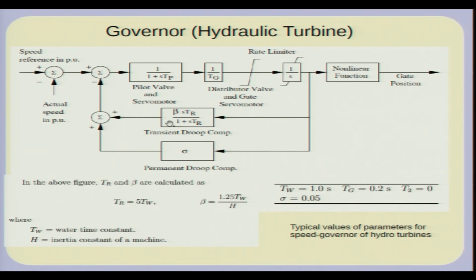And for a hydraulic turbine, it may be slightly more complicated. As I mentioned here, you may have a gain which is somewhat low. You may end up having a control system which has a behavior that is different for fast changes and for slow changes. This is something which I will not discuss here. You can try to model this control system on XCOS, which is shown here, and see how the behavior is when you have different beta and gamma.